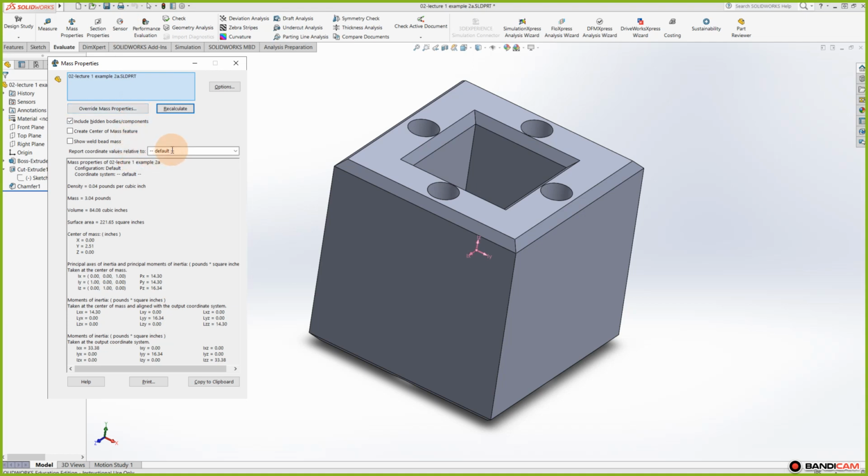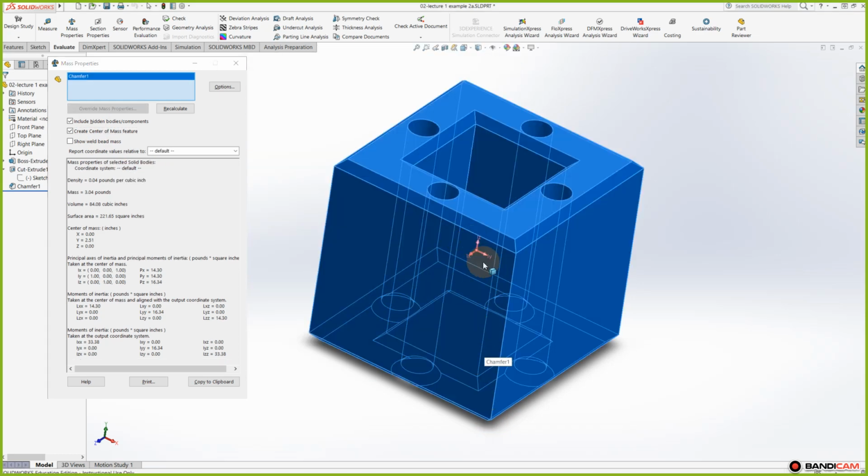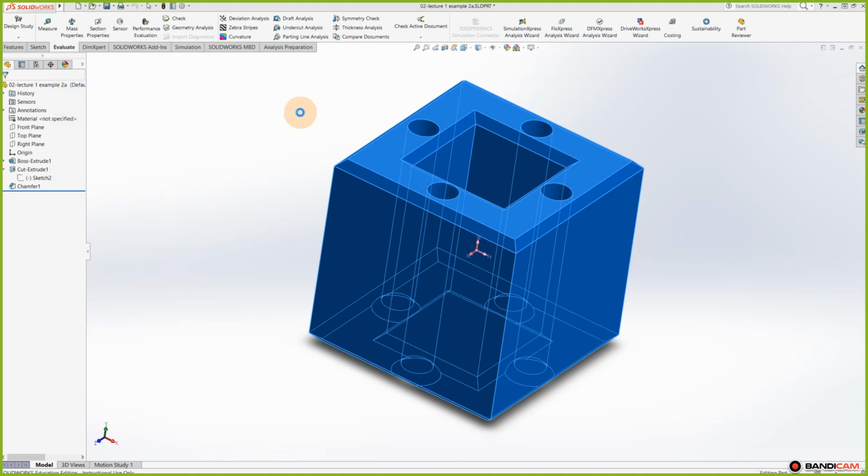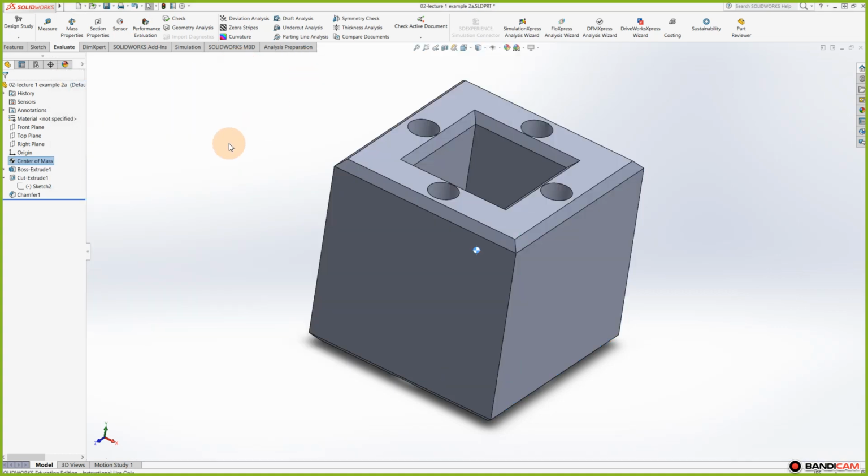You should be able to change the center of mass as well. If I go change the center of the mass, and I click this piece here, it's now in the center. If I were to go recalculate, you notice that the number has changed as well. It should have changed. If not, when we get to the material, I'll go into more depth of that as well. So that's just little features you can work on when using SolidWorks in work or at home or just to play around with. So now back to the interface of SolidWorks.